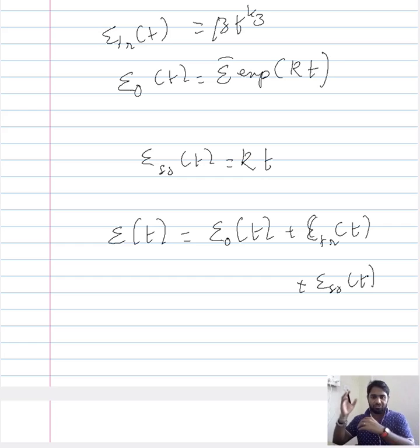And ultimately, the tertiary stage is not included in this expression because the failure of the material is so quick as to warrant no inclusion. The experimental observations showed that the stage after the steady state creep is so fast that it cannot be adequately included in this expression.